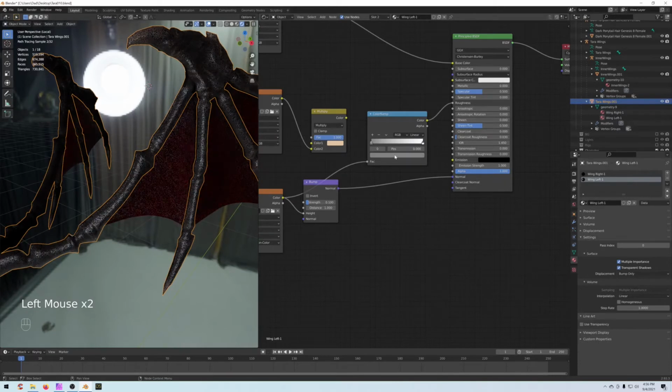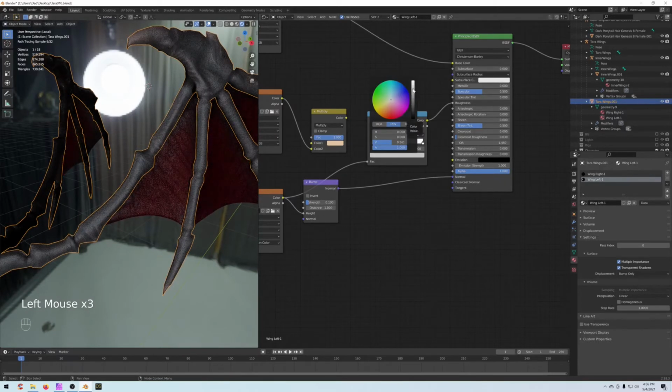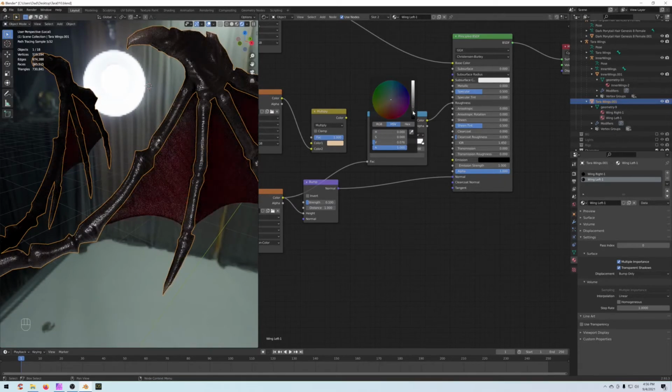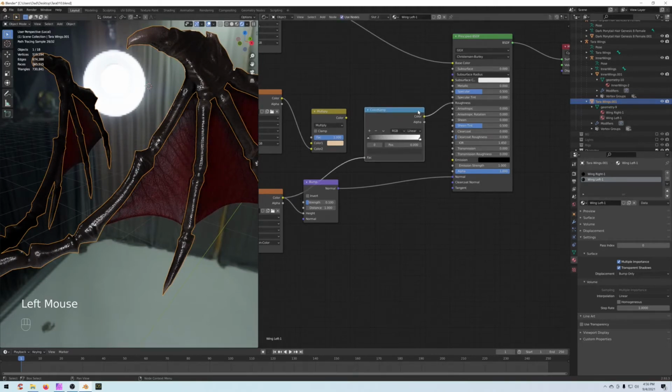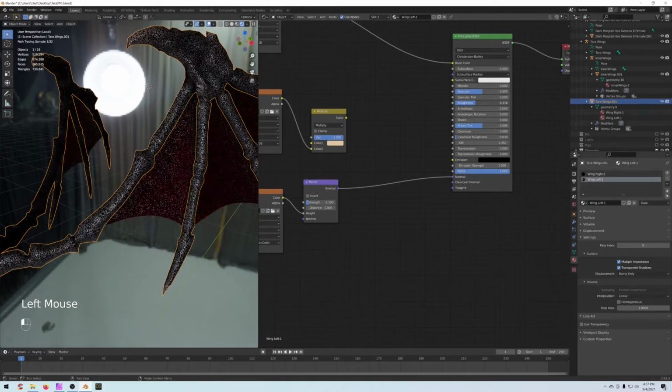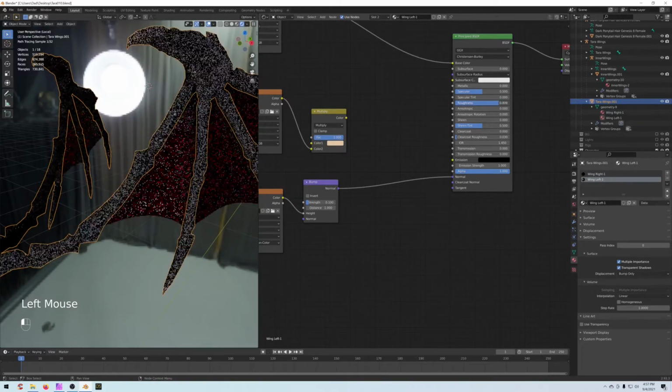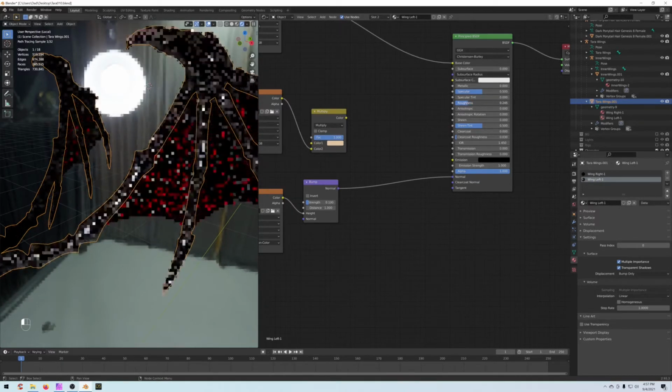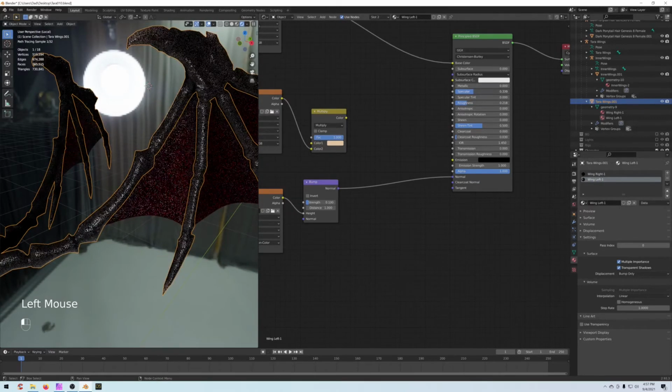And let's see here, lower the blacks a little more. Nope. Not really getting what I'm looking for. So we'll just adjust the roughness. Spread out way too much. Maybe if we lower the specular down. Yep, that actually looks better.